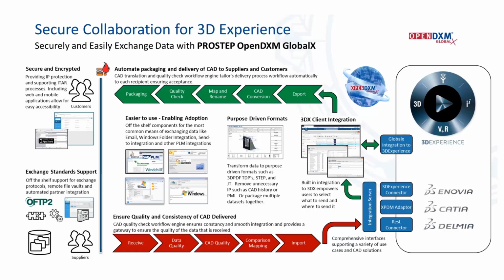And then on the import side, supporting different data formats like OFTP2 and EngDat. Be able to take data from your suppliers, import it, check the quality, so make sure the attributes are right, make sure that all the data is there that you need, examine the CAD and do a CAD quality check, and compare it to what is already existing within 3DX and import it there too. And this uses the similar technology to OpenPDM and leverages those connectors. So it'll give you, powered by PLM collaboration interfaces, as well as 3DX and new REST connector too.